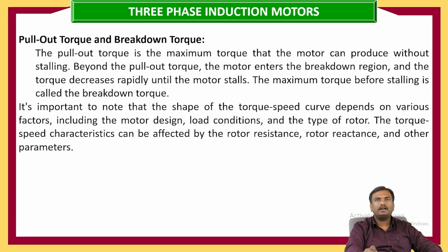Beyond the pull-out torque, the motor enters the breakdown region and the torque decreases rapidly until the motor stalls. The maximum torque before stalling is called the breakdown torque.